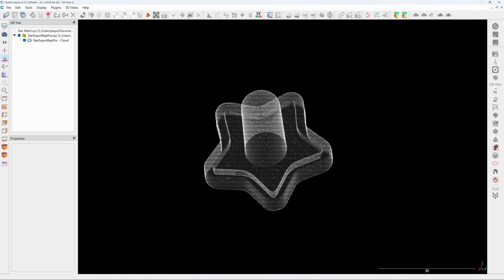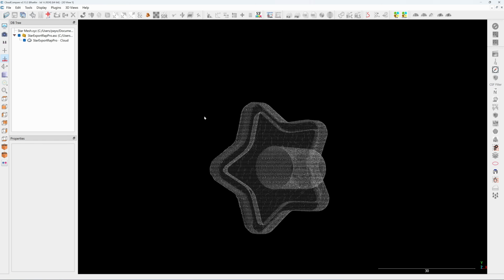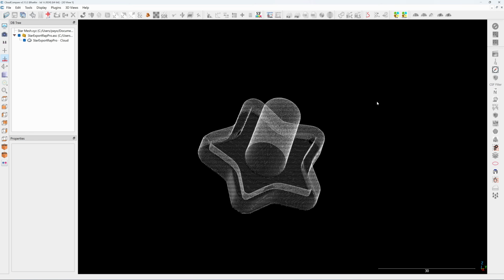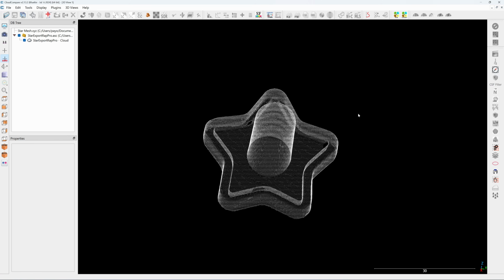Okay, next if I click on the top view, you see that the scan data is not aligned to the XY plane. See here, this is the front view. It's not aligned. So to start reversing, it's quite necessary to align your object to the XY plane. So you need to pick one of the flat planes and make it align to the XY plane. This is the reason that I import the point cloud into CloudCompare, because it has this function.